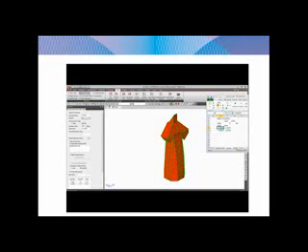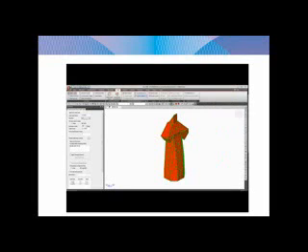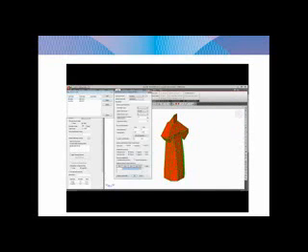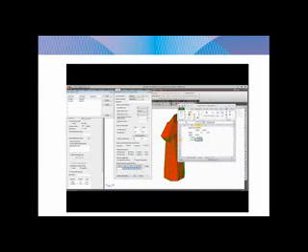So press modify. We have the seismic load direction factor. So X, since it is in the first quadrant, should be all positive. Same also in the ortho. Go to analysis, then perform analysis again.